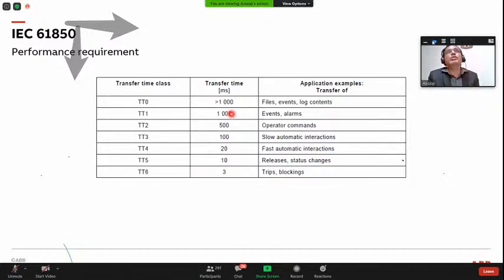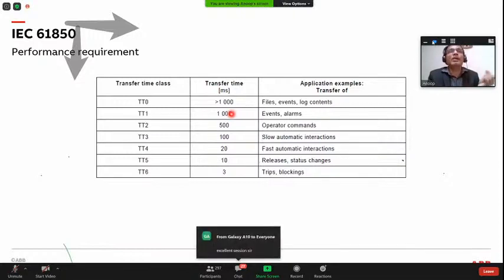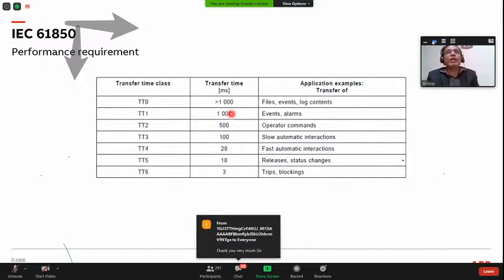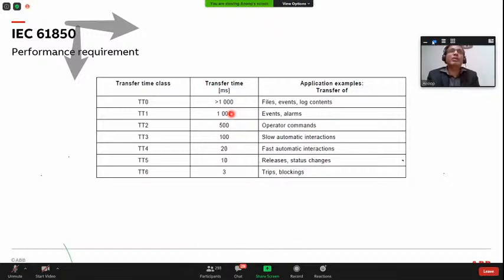Then I introduced you to different levels in substation automation: process level, bay level, and station level. Process level is where all the current and voltage is; the real action happens at high current and high voltage. Then you have the bay level, where devices look at the process level to monitor and control. Then your station level looks at the complete substation. I also introduced an entity called the merging unit, which saves kilometers of cables by digitizing current and voltage into digital samples.